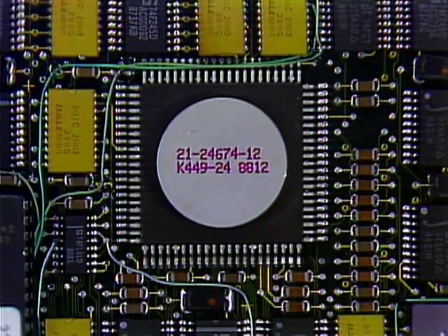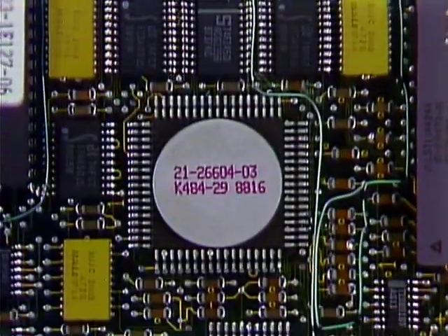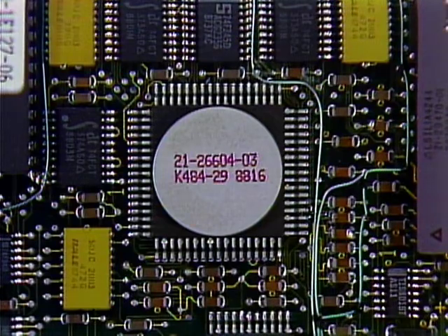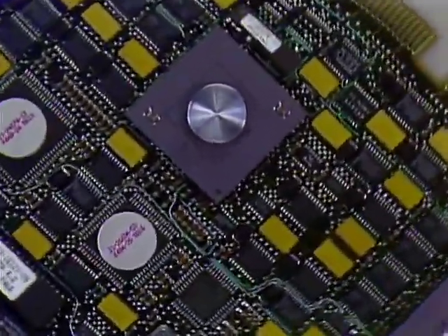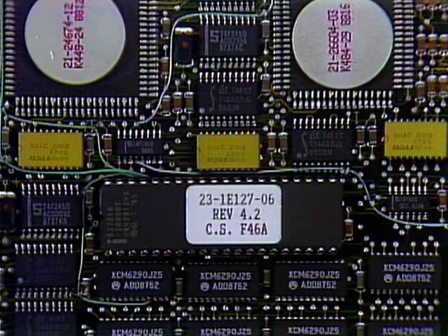To accelerate floating point operations, each CVAX has a companion floating point accelerator, or FPA. The FPA supports VAX floating point instructions and operates on F floating, D floating, and G floating data types. It also accelerates execution of certain integer instructions. The diagnostic boot ROM provides a total of 128 kilobytes of system boot information, as well as self-test diagnostic firmware for each CPU.